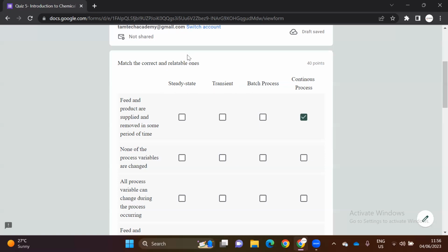What does it mean? If you're controlling the reactor in terms of temperature control, let's say your reaction should be going around 300, right? So it should be kept the same, at 300, because your reaction is adjusted to 300. But if there is an increase in the temperature, for example, 350, 400, or 500 something, it means if it's exothermic, there will be a huge amount of heat release, and this reaction will be a runaway reaction. It's undesirable.